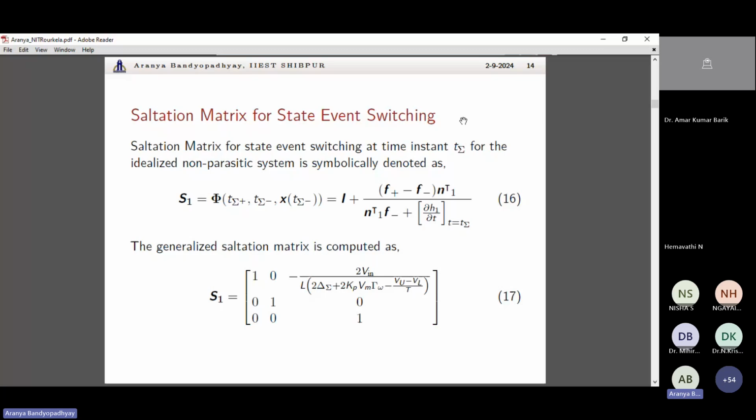For predicting that type of instability, you need to take into account either some discrete type of method, or a Filippov method that I have considered, or the trajectory sensitivity approach of Ian Hiskens. Hiskens' trajectory sensitivity approach is widely employed in power systems. Since 2008, the Filippov method has been widely employed in power electronics systems.